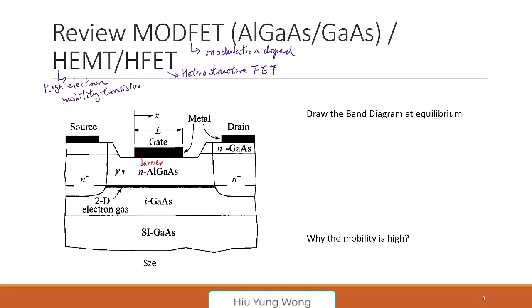Now you start seeing something very similar. We talk about gallium nitride, we say it is HEMT. Oh, this is also HEMT. What does it mean? We just talk about heterostructure. Oh, this is also heterostructure. What does it mean? And what does it mean by modulation doped? So this is an old structure people have been using in RF using gallium arsenide. And now what do you see? This one doesn't have polarization charge.